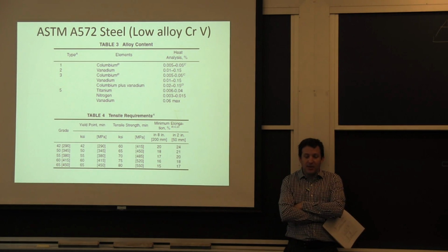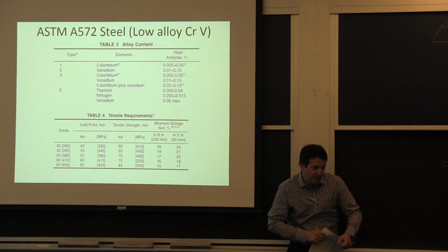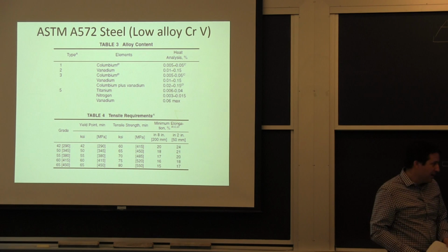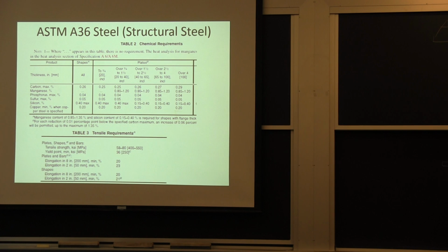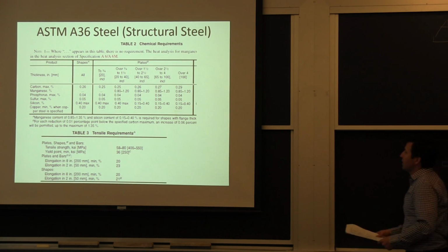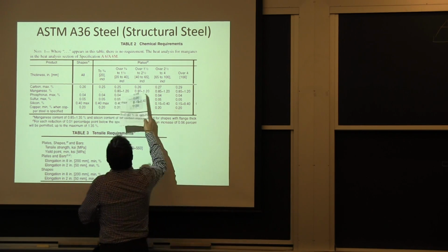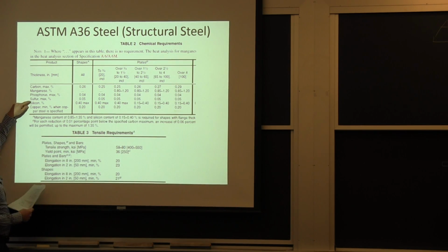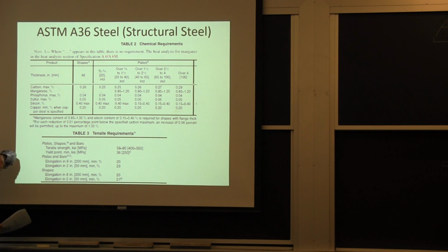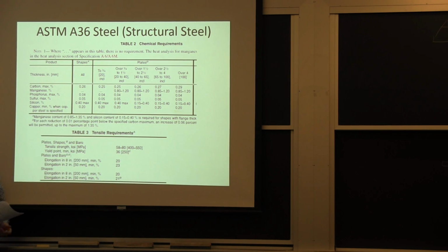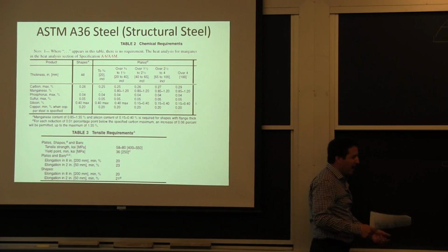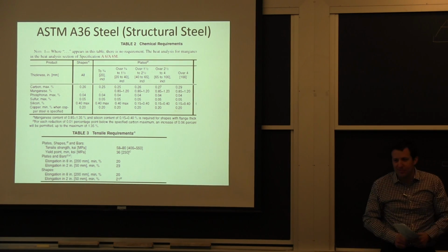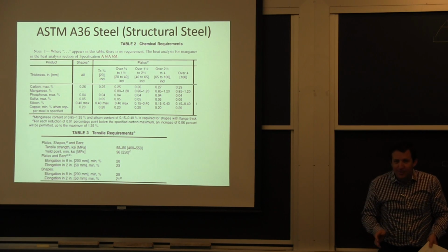So this idea of getting at least one number of the chemistry was typically the way I was treating this. I was going back to the ASTM here, and I was able to say, okay, for the shape I have, do I meet the sulfur, phosphorus, manganese, and silicon requirements? And if I did, I loved having some indication that my material properties were okay. But that's not easy.